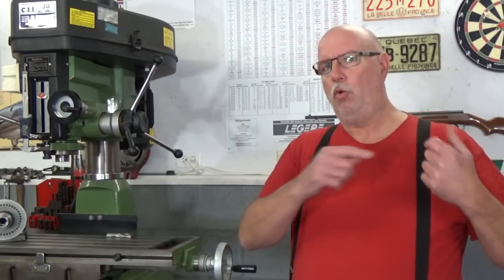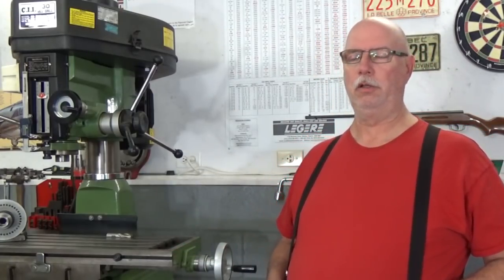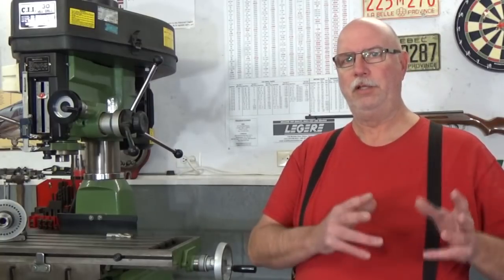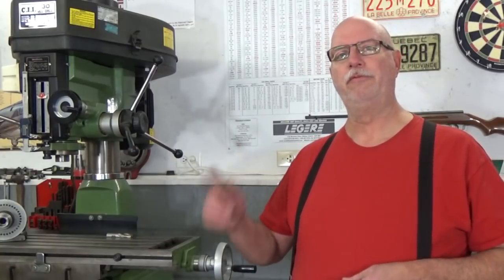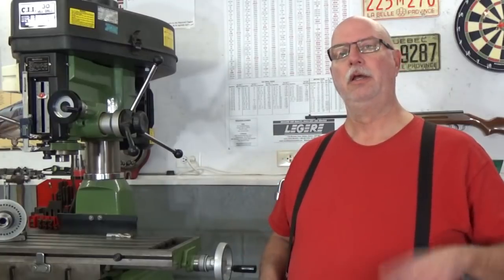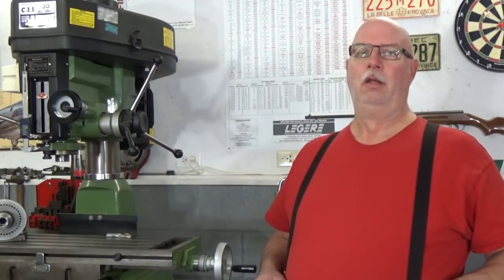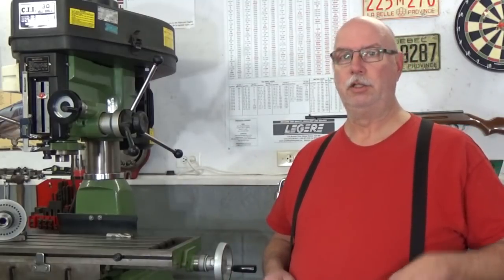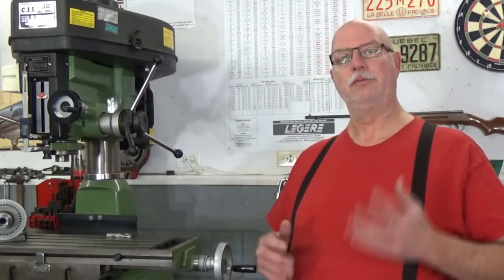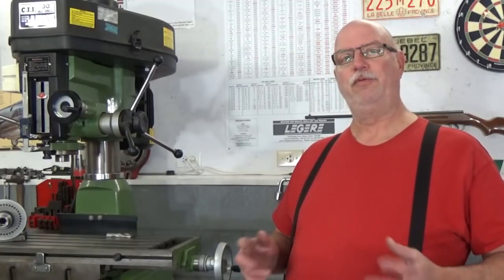But what about our 1/4 20 thread we mentioned earlier? Again, 1/4 major diameter, 20 number of threads per inch, not the pitch. The pitch is 1 inch divided by 20. Because there's 20 threads in 1 inch, and 1 divided by 20 is 0.05. So 50 thousandths of an inch is the pitch of a 1/4 20 screw.